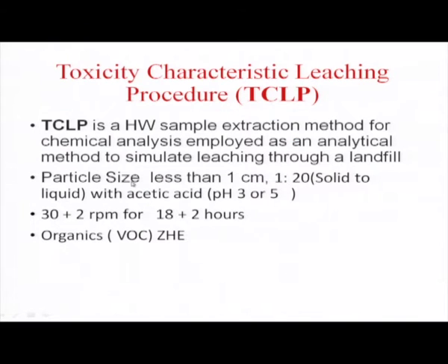And there are some specialized TCLP tests. It is not a kind of orbital shaker that should be used for carrying out the shaking. In the laboratory, normally any shaking we will do in an orbital way, but it should rotate in this way. Okay. The sample should be rotated thoroughly in a mixing with acetic acid, so that the entire portion of the small particles of this solid waste is getting exposed and ultimately leached out. So, the laboratory based orbital shaker may not be good for this TCLP.